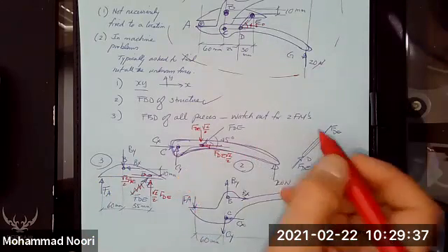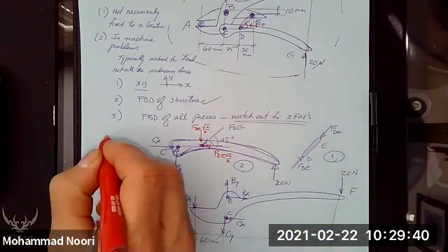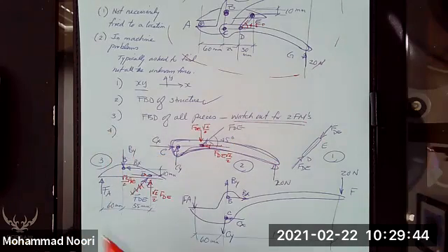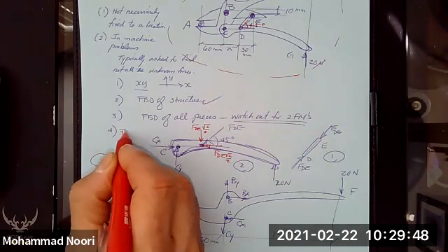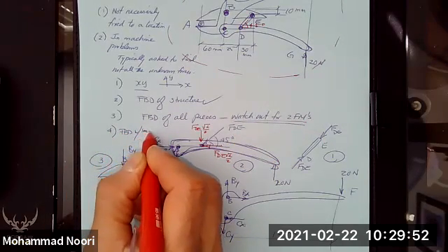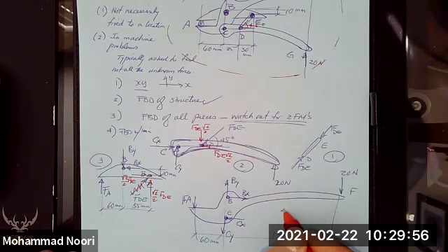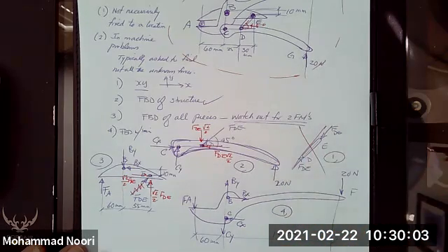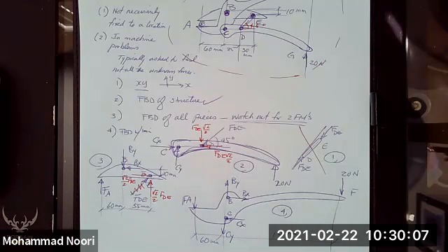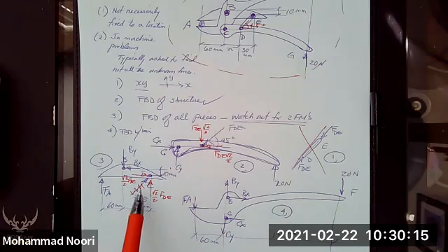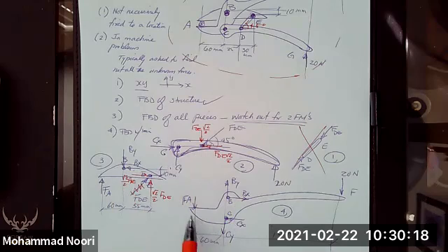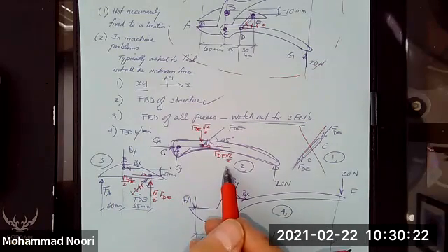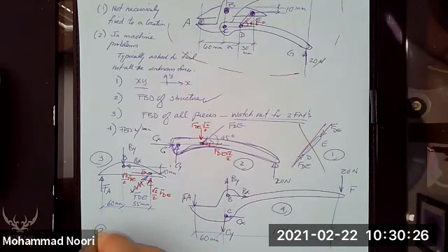Sure. That helps. So it comes out to this. So you drew the free body diagram, you watched out for two force members. So the last phase is start with a free body diagram with minimum number of unknowns and move on. So I have one, two, three, four free body diagrams, right? So this one is already out of the picture, right? I cannot use that. So I have three of them. So let's look at it, see how many unknowns I have in each. Here, one, two, three, one, two, three, four, one, two, three, four, five. So obviously, I'm going to start with this one, right? So let's start with free body diagram number two.